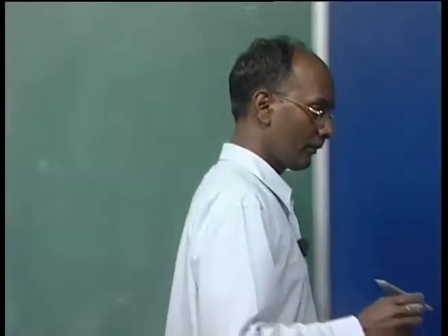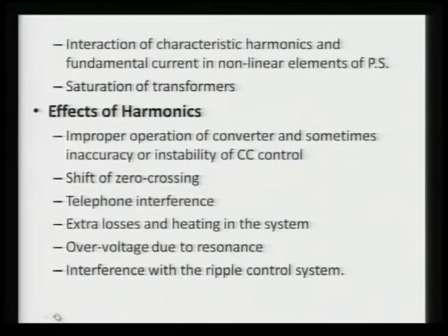Another cause is the interaction of the characteristic harmonics. Already we are getting the characteristic harmonics, your 5th, 7th, 11th and 13th. If those interact with your fundamental component and there are nonlinear elements in the power system, even inductors are still nonlinear, then they are going to interact and that creates a problem.